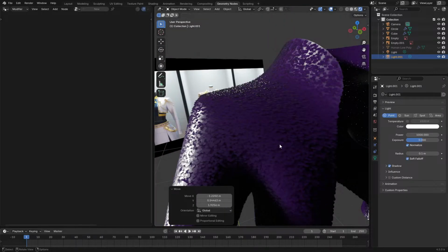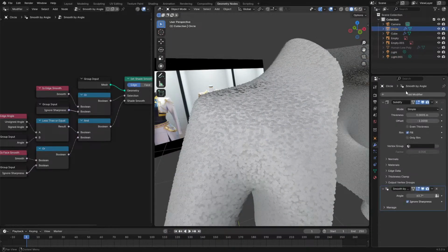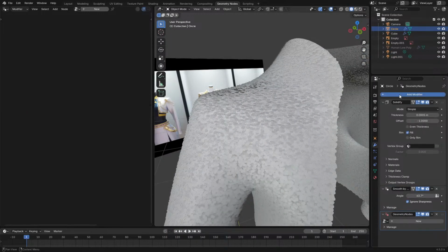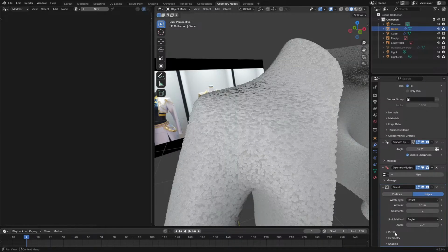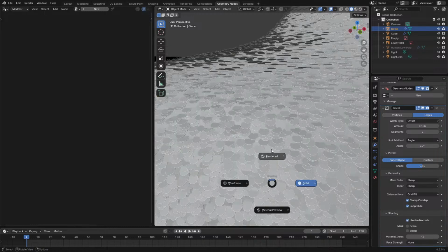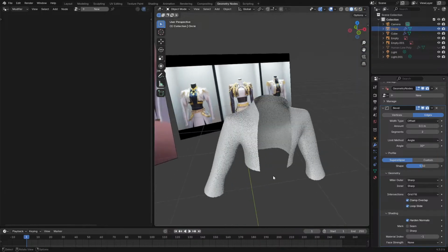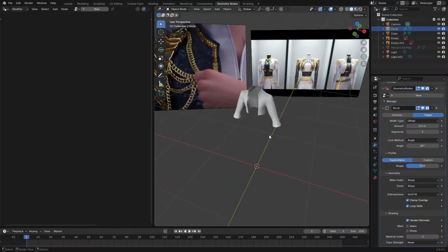Okay. I can make this even worse on myself by beveling the circle. So let's go and do that. Bevel. Let's set it to be 2, profile, no, geometry, nope, shading, harden normals, because I want that little glint that's there. Okay, we're getting there. We're getting there. It is so laggy.